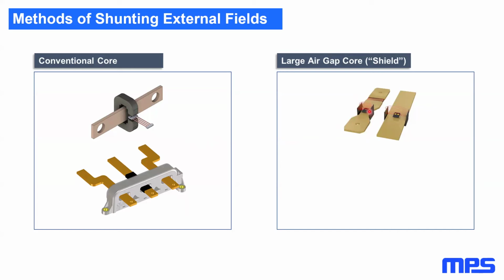It's a core. You have this large air gap, which, like I said, allows you to have less material, but it also means that it doesn't shunt away the external field nearly as efficiently as the closed C core. But this is considered a kind of evolution forward from this because it's less material. You have an IC. It works. It's kind of a pain in the butt. You have to do a bunch of simulations to make sure that you have enough flux, but not too much, that you're shunting the flux from the actual direction that you expect the interference to come from.